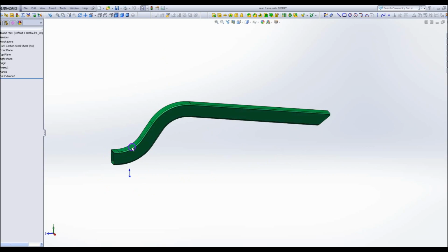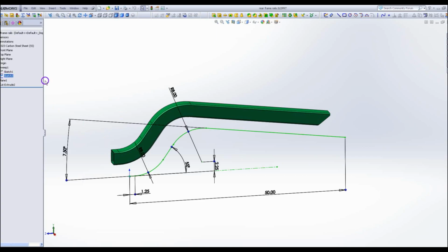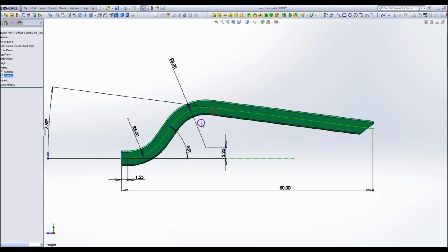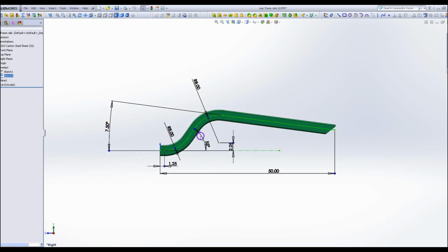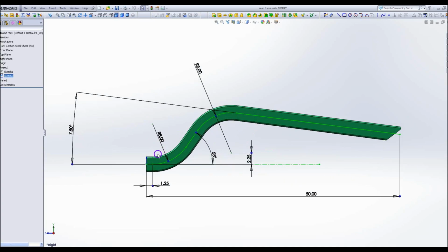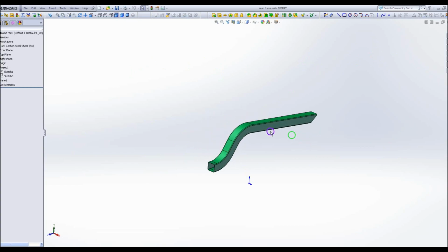I think I got a pretty good idea. The radius of these things that Ford designed it to, they're nice even inches. They didn't use millimeters in 1968. Even angles. So I'm pretty sure I got this pretty close, but it's not going to be exact. So if I take a piece of bar stock, bend it to the inner contour, and use that to make this side plate, then it'll be really close. So that's what I'm gonna do.